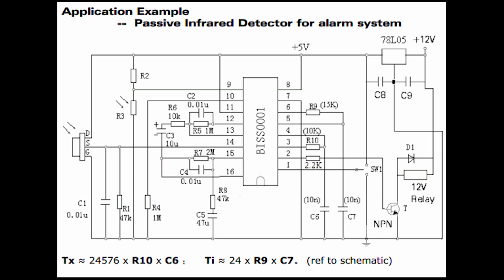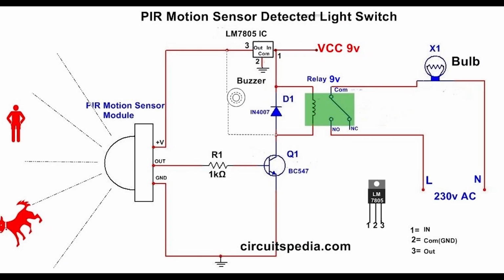The pyroelectric materials can detect changes in IR radiation level, which occurs when warm objects such as humans move within the sensor's field of view. The PIR sensors use a special lens called a Fresnel lens to focus the infrared radiation onto the pyroelectric sensor. The lens is designed to divide the detection area into multiple zones. As a person moves across these zones, the amount of IR radiation hitting the pyroelectric sensor changes, causing a detectable variation in the sensor's electrical output.